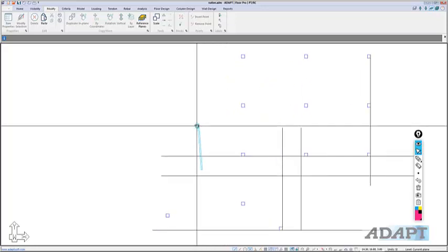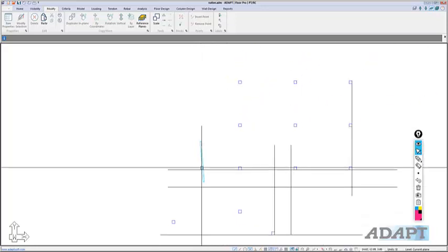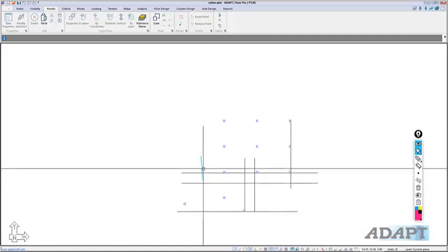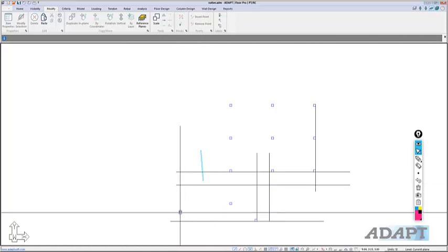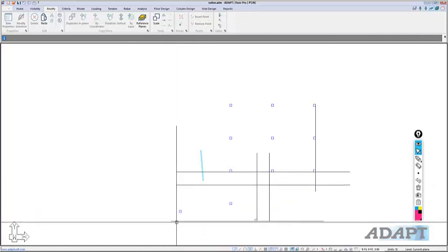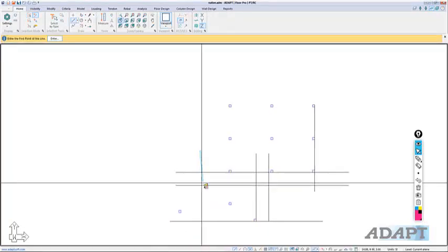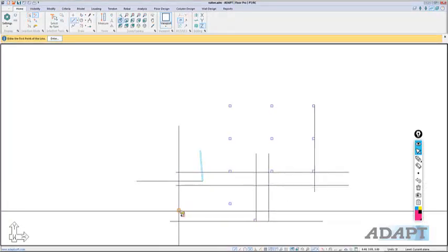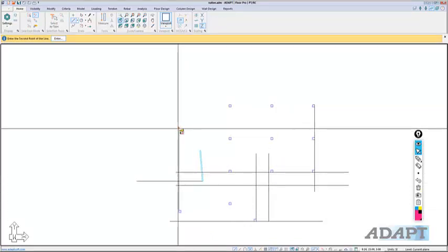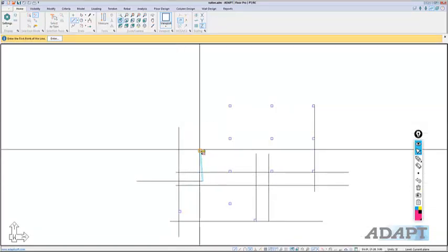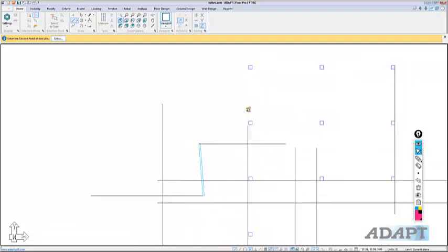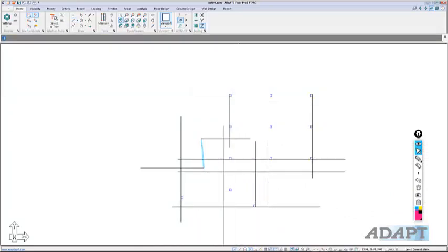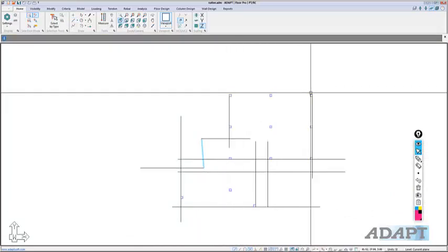We want the slab edge to align with the corner, the edge of this wall. And then it will, from this point out, it will be aligned with the edge of this column down to this line here. Okay, so we need a few more reference lines. And I'll grab that and just come back over the top of it. And then from here, I want to go from there out to there and something like that. I don't really need one up here because I already have 2 points I can snap on.